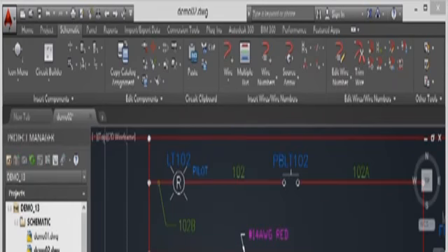So you select the attribute text and it rotates it in 90-degree increments. So if I click on Power there, it rotates it 90 degrees. If I click on, rotates it 90 degrees. Now the problem that you have is as soon as you do this, you then need to press Enter to finish, and you might need to move those bits of text. Now I know it doesn't look perfect, but it's very easy to sort that one out.